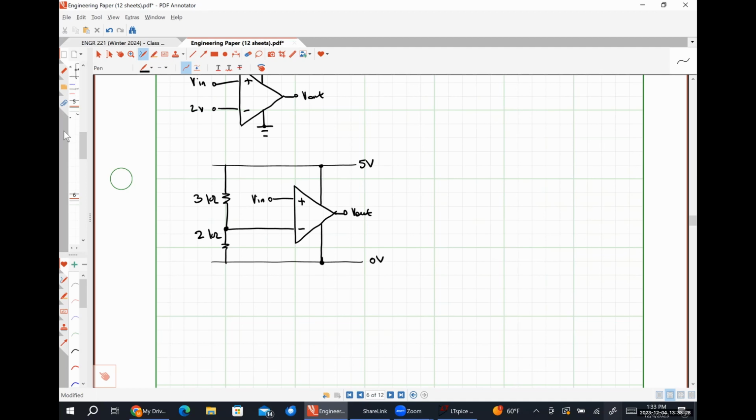For part C, then I start screwing with the supply voltages, which means you're gonna see things cut off and saturate at VCC plus and VCC minus. So it's literally just gonna be this curve, except parts of it are gonna be slashed off the top and bottom. Oh, so it's a cutoff right there. Yep, and then we'll cut off down here at whatever voltage is appropriate. And for part C, you're just telling me what those cutoff points are. Part D is the exact same thing, except a different set of supply voltages.